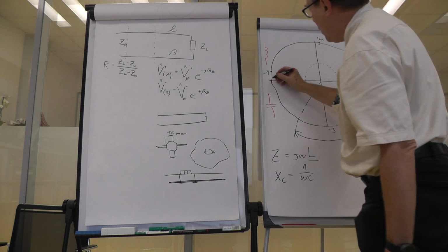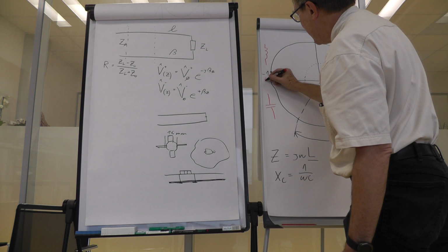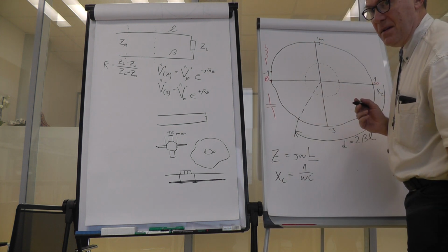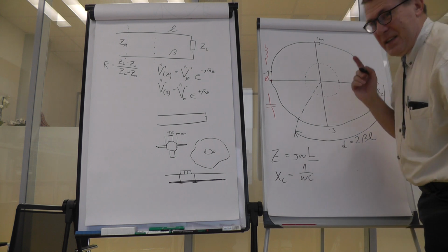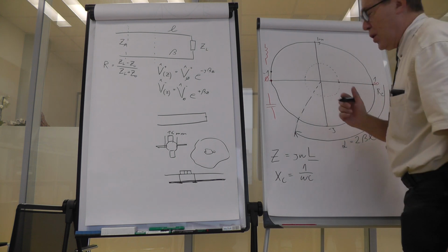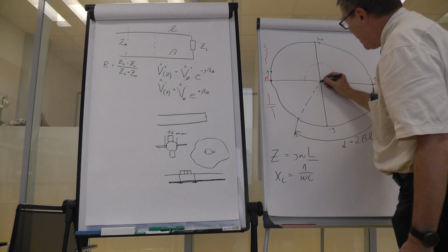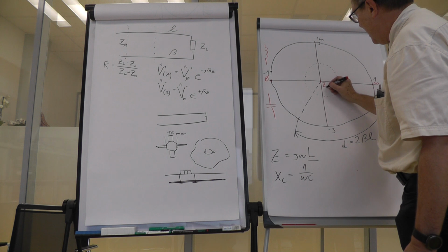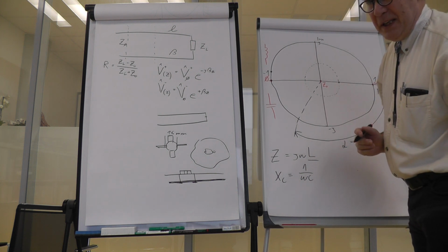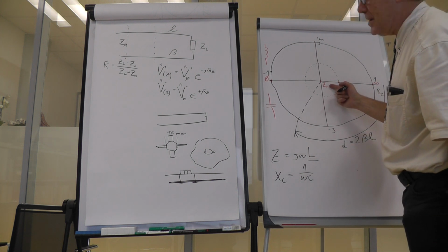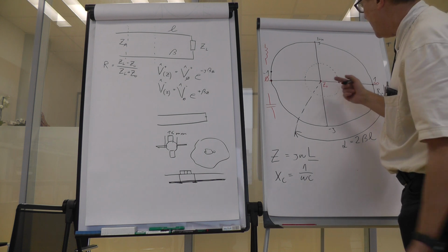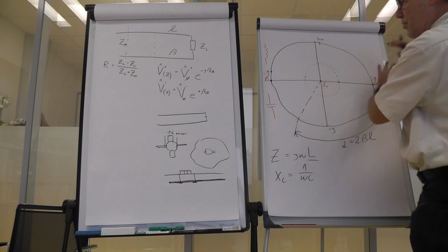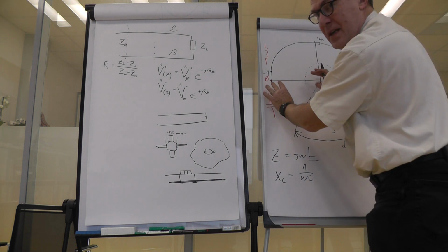This is caused by an impedance of 0. Now we already know one more point. There is no reflection, and that is caused by a load impedance equal to the characteristic impedance of the transmission line. So now we know 3 points that we can attribute both to reflections and to impedances.